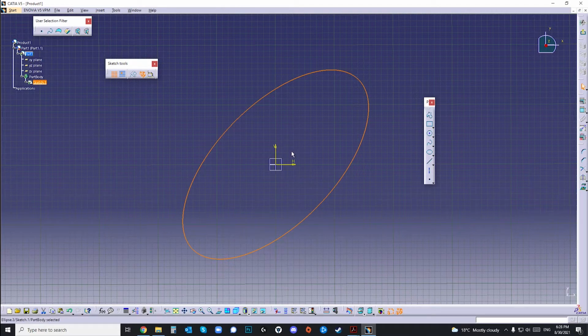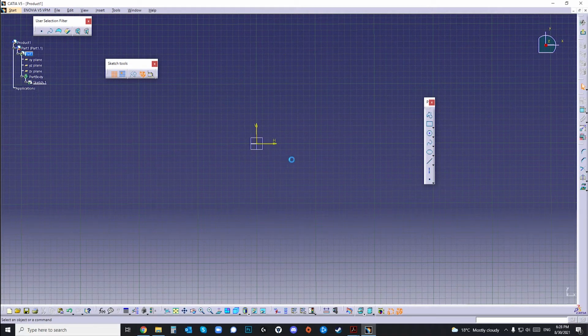So when you want to angle, in this case the ellipse, you have to keep in mind that the software will place the ellipse keeping the trigonometrical sense, or the counterclockwise dimensioning. So please keep that in mind. Okay, so this was the ellipse.